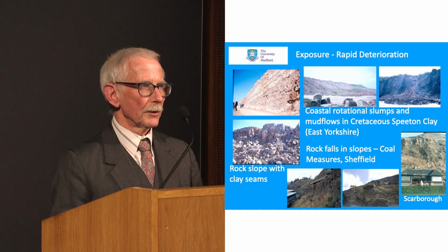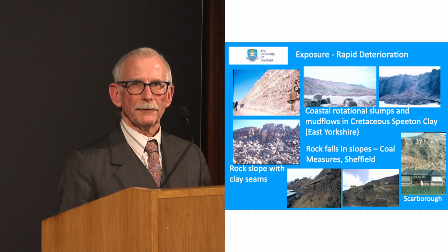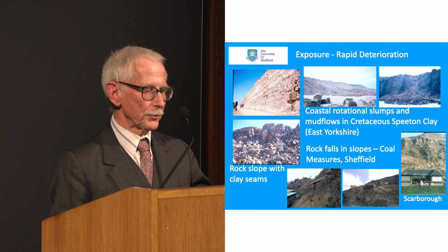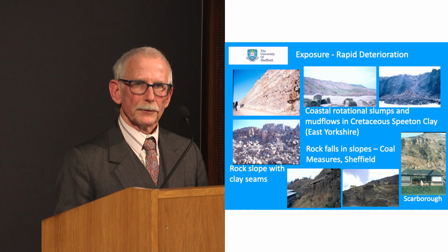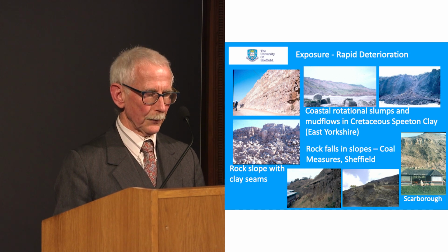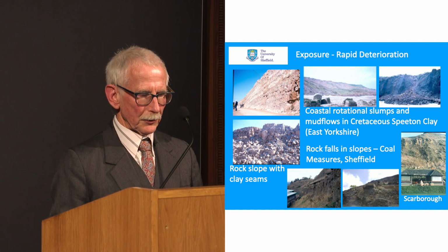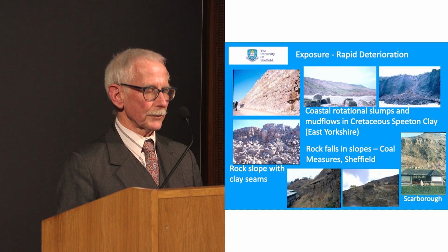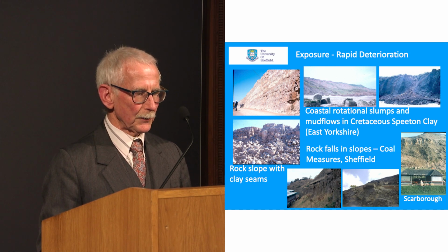In some cases, the mud rock might be a very minor part of the sequence, such as the slide on the left-hand side, which shows mainly limestone, but there are thin seams of mud rock between these limestone beds, and because of the weathering of the mud rock, what looks to be a very stable slope will become unstable in a couple of years. In some cases, the mud rock is the majority material. The slide at the top right shows Speeton clay in Yorkshire. The failed material rapidly degrades into mud flows that spill onto the beach.